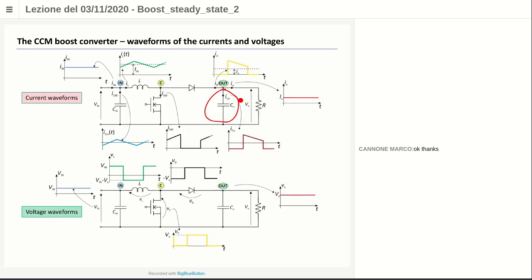I don't know, say 24 volts. You can have, say, 45 or 40 volts as a maximum voltage here, but the voltage does not diverge; it goes to a very high level. So the electrolytic material inside the capacitors heats up, and this brings about the explosion of the output capacitors.